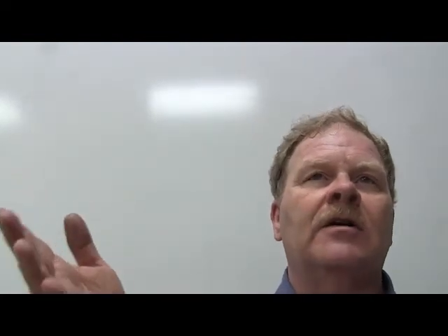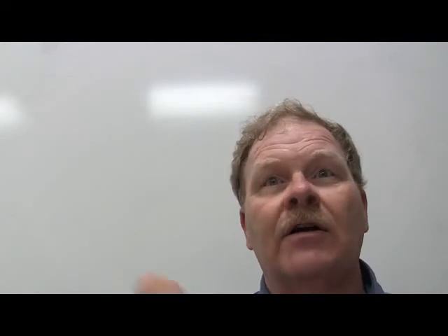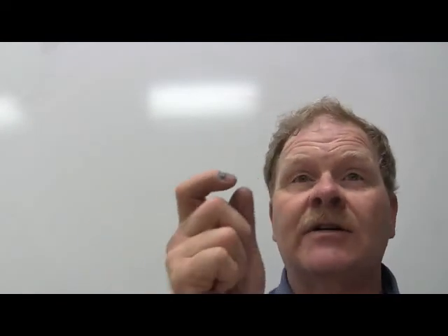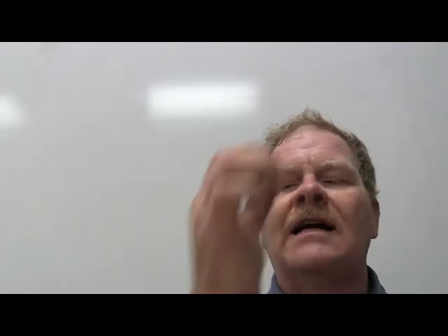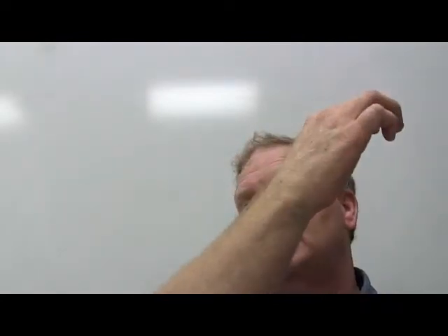That's true. You know how much voltage is coming out of your finger? You know how whenever you grab something and it pops, it gets you? Like if you're walking, that's from 8 to 25,000 volts. It's coming out of your finger. That's why it jumps that gap. But if it goes into that electronic part, it's done. So you've got to be careful about that. Don't they have a wrist strap you can put on and ground it to the case before you ever do that?